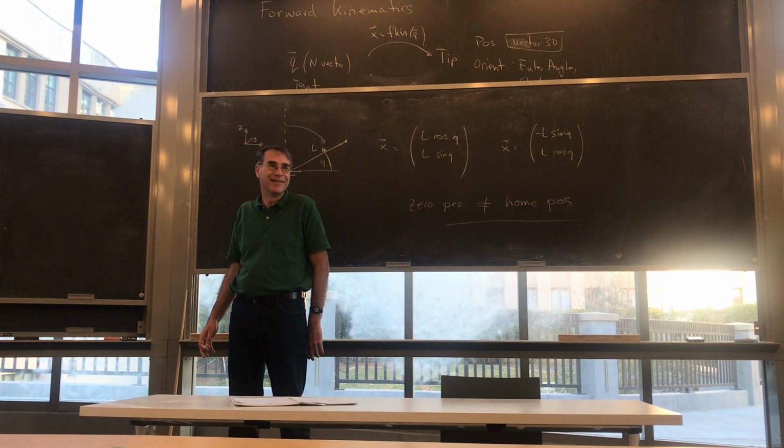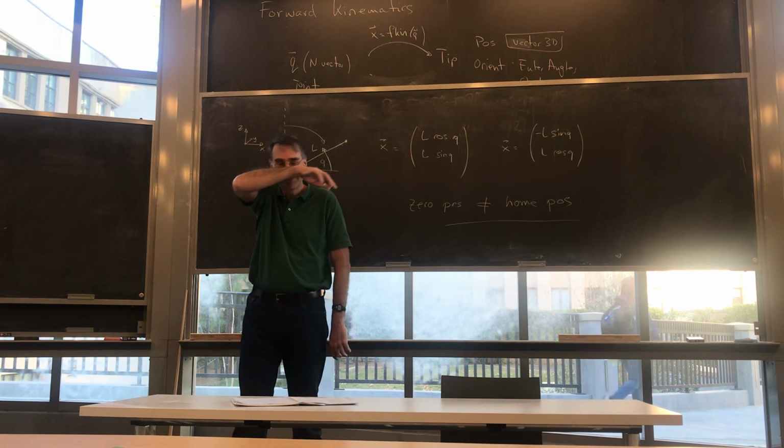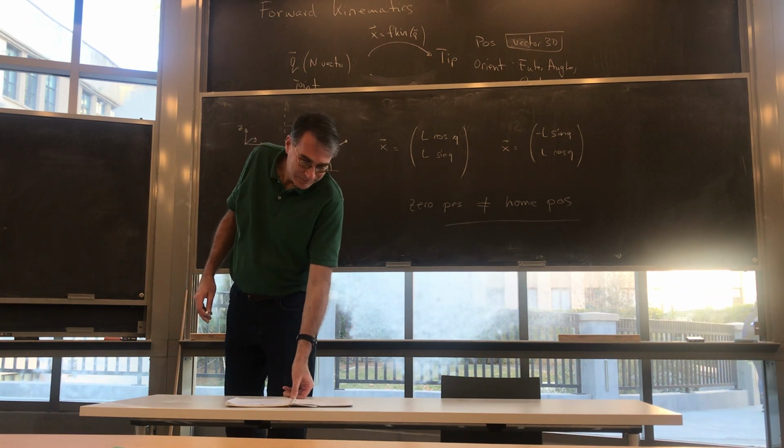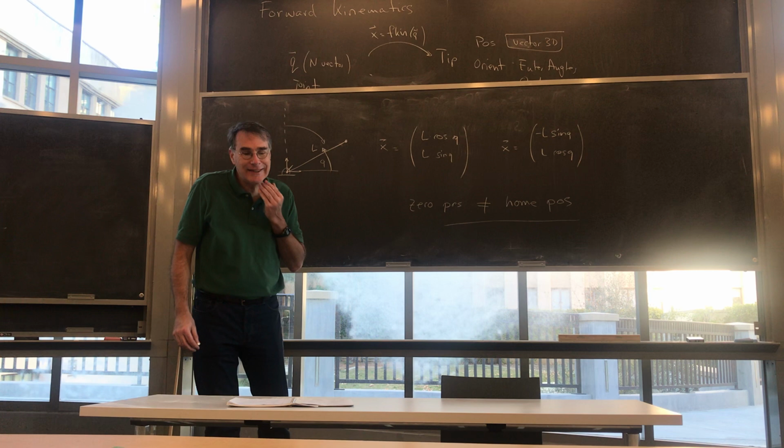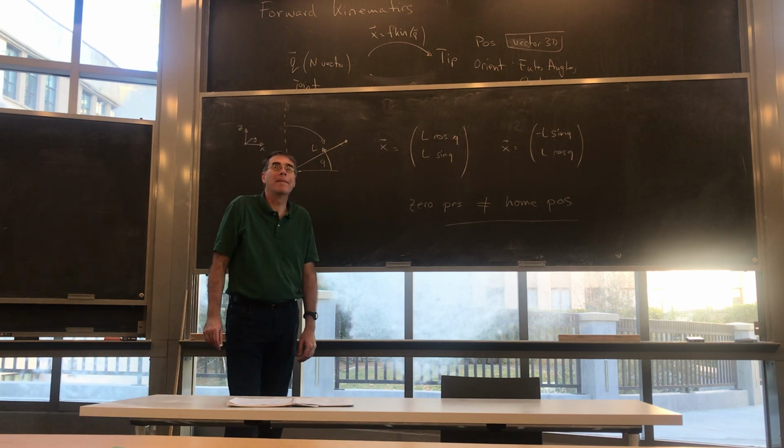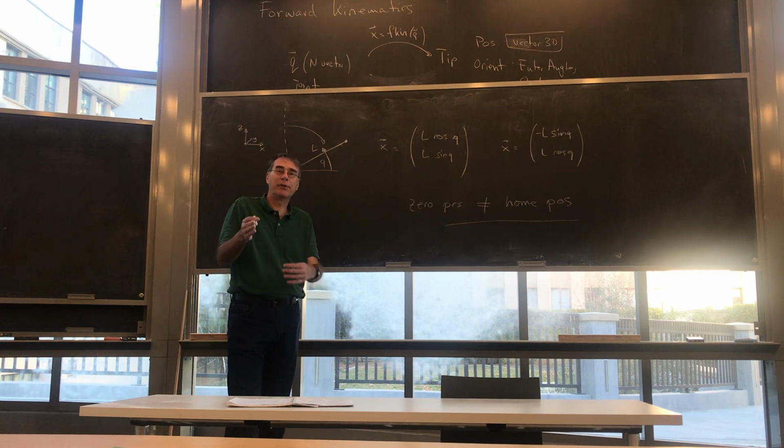I was going to say, the zero position is what all your coordinates are with respect to, but your home position might be the orientation of the robot that you want it to be in when it's not particularly at a target location or pose. That's absolutely right. It is kind of an arbitrary English language definition, but zero position, I mean, this is where my joint reads zero. There are sometimes systems where you can't actually get to zero.